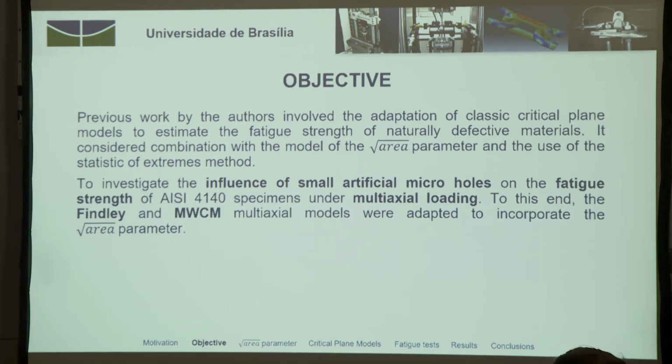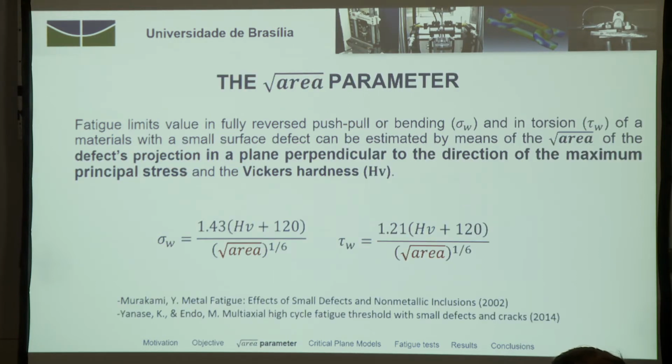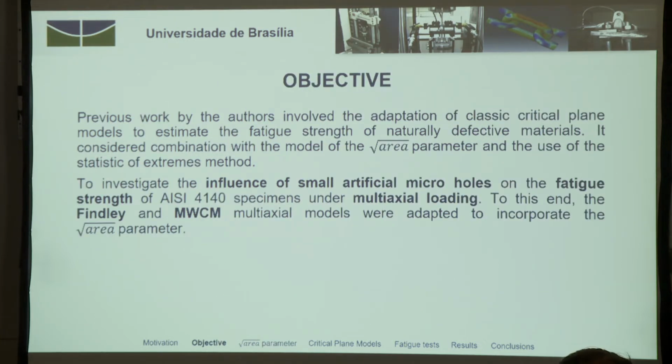For contextualization, we have also performed recent work on this theme, where we analyzed the non-metallic inclusions in this material, and we combined the multiaxial critical plane approach with the square root of area parameter to predict the fatigue limit of this material.